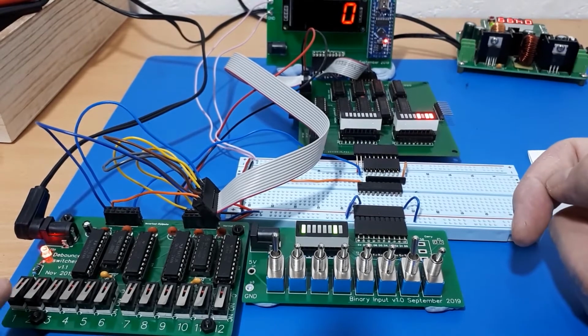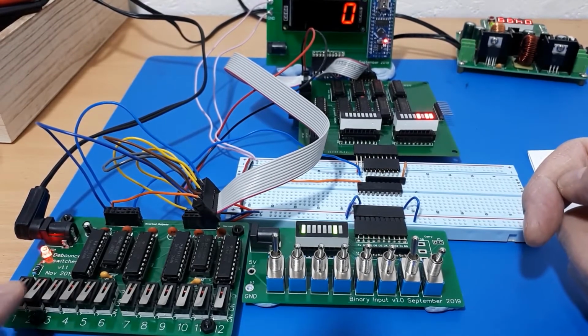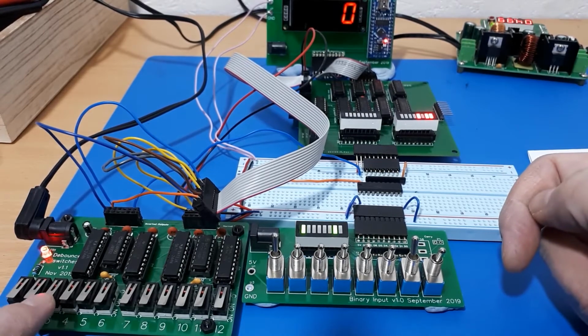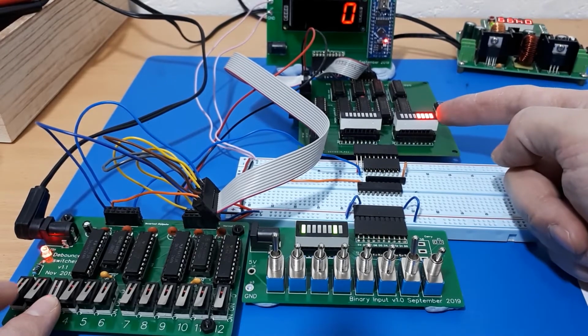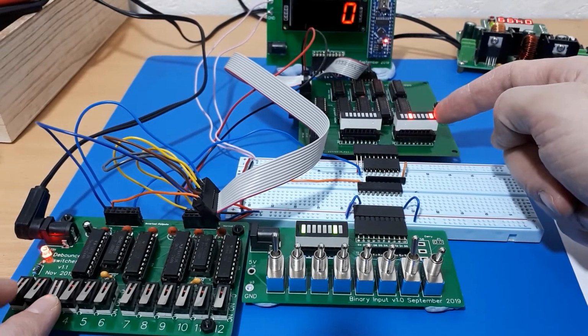So if we do the clock cycle without holding down the increase button, nothing happens. If we just press the increase button, nothing happens. You've got to hold the increase thing in a low state. Is that a low state or a high state? That's a high state, actually, sorry. So we bung it into a high state, and we do a clock pulse, and then we increase the program counter. Now, obviously, we're only increasing the bottom 8 bits at the moment,